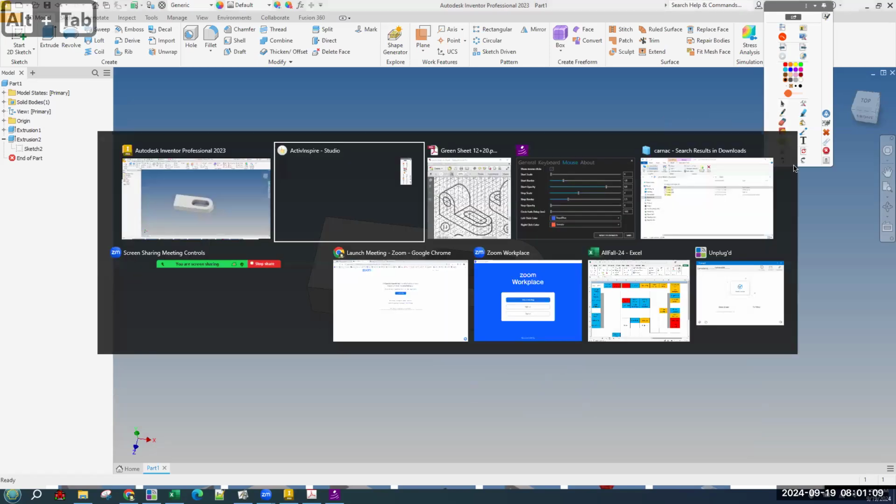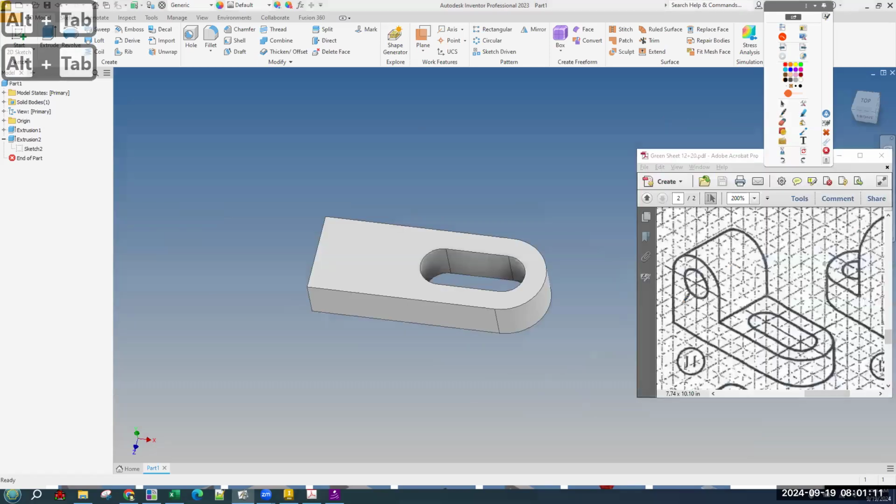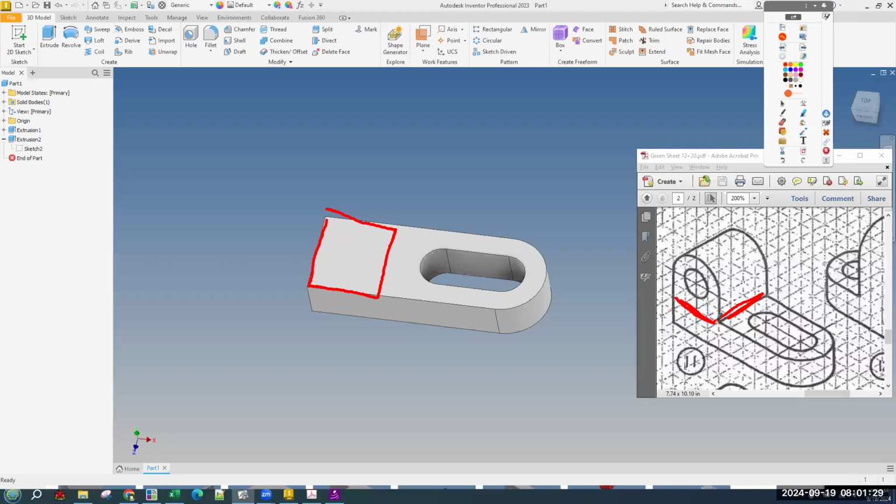Okay. The other part, we are going to sketch on the surface that we already have and draw a rectangle that's 4 wide and the entire distance front to back. So we're going to make a rectangle this big, which the entire distance front to back is also 4. Okay, so we're going to make a distance of 4, and then we are going to extrude it up 4.